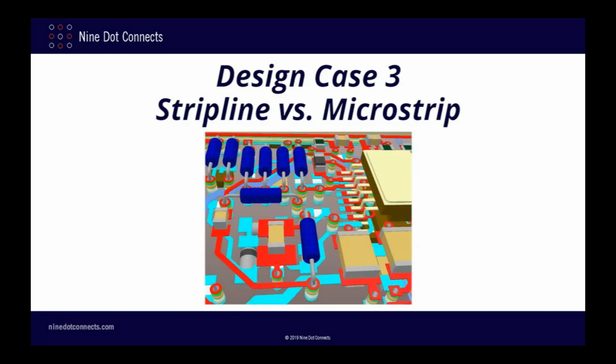When the board consisted of all through-hole components and vias, the routability of each layer was pretty much the same anyway. The use of surface mount technology parts, or SMT, changed the equation a bit by removing the need for through-hole mountings, therefore somewhat increasing the routing area on the inner layers. However, over time, things changed, and I was forced to grow up and leave this simple innocence behind.